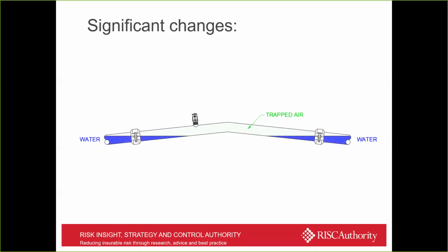So that pressure difference is unlikely to move that air out of the top section of those range pipes, and therefore those range pipes won't flow any water, which the hydraulic calculation allows them to do, or takes into account.